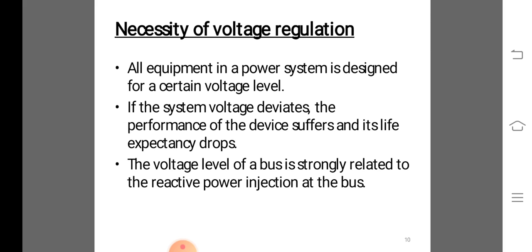The generator terminal voltage Vt is compared with the voltage reference Vref to obtain the voltage error signal ΔV. This signal is applied to the voltage regulator with the transfer function Ka/(1+Tas). The output of the regulator is then applied to the exciter with a block of transfer function Ke/(1+Tes). The output of the exciter EFD is then applied to the field winding, which adjusts the generator terminal voltage.